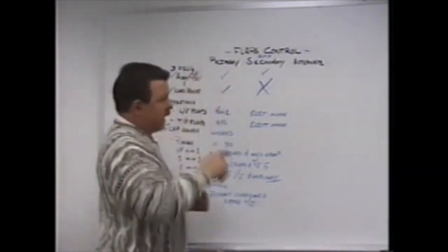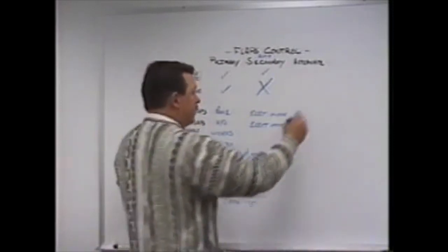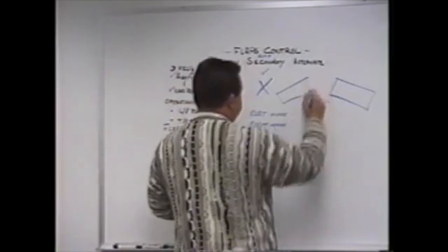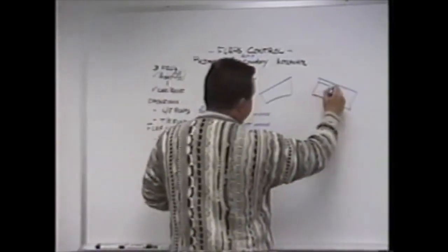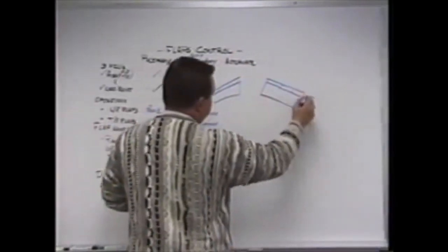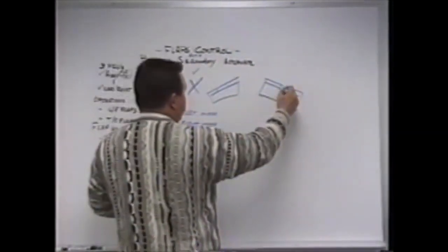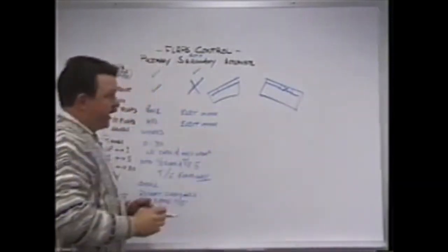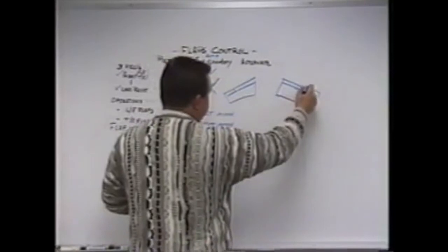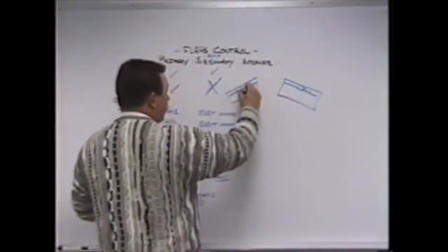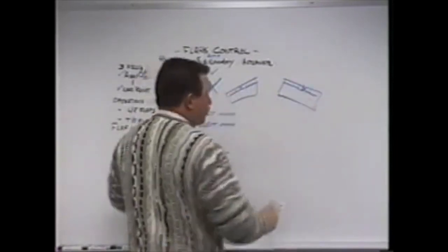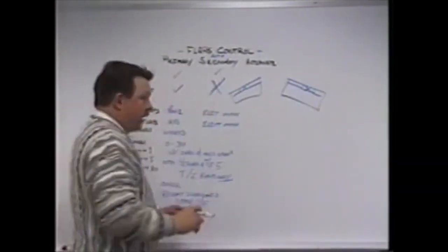Leading edge flaps. Let's just draw an example here. Let's say we have our left and right wing. These are not to scale, by the way. You've got the inboard segments, the midspan segment, and the outboard segments. If I was to encounter a problem with the right midspan leading edge flap, the asymmetry protection would deploy the midspan electrically on the right wing and the left wing. So the asymmetry protection will drive out both sides electrically. Everything else will continue pneumatically.